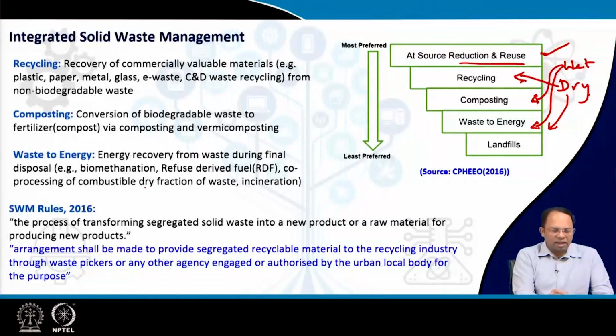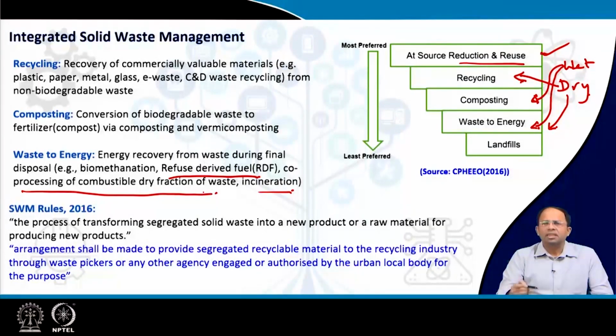So we have incineration, or we can convert it into a material which could be used as a fuel for some other industry, so refuse derived fuel. Or it could be used for co-processing of the combustible dry fraction of waste, like in the cement industry and other industries, where we can use this as a material for co-processing and for burning or generating energy, right? So this is where dry waste also could be utilized. Once all this utilization is done, whatever remains goes into the landfill, as we just discussed earlier.